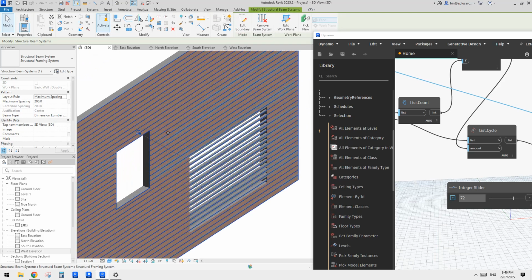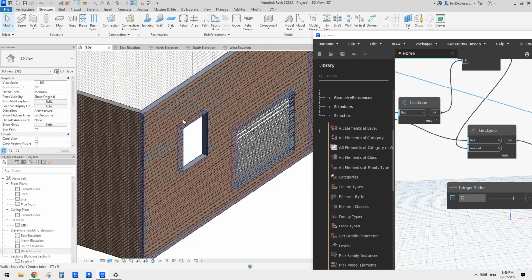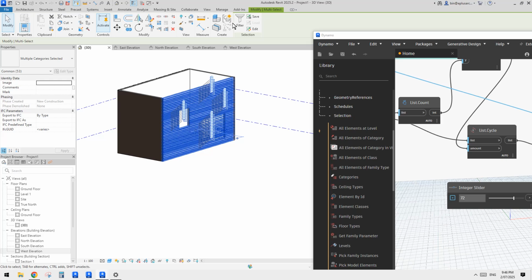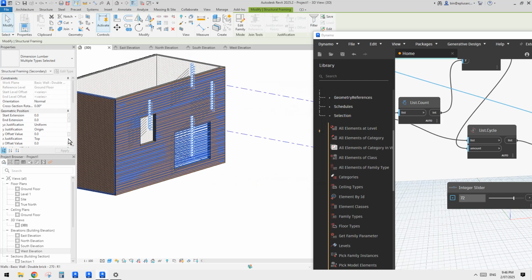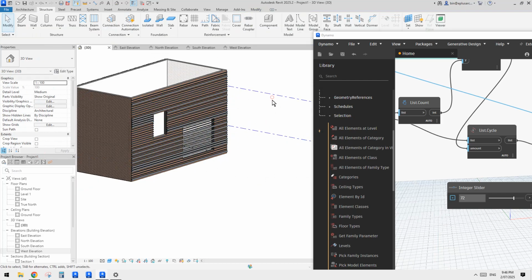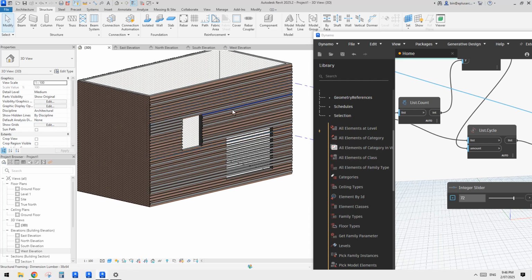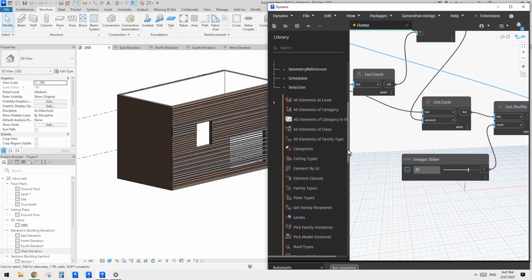Yeah, good. So again, you can see that inside of the wall, but this time maybe I'll just select them and filter. I'll just unselect wall, beam system. Yeah, select all the structure framing. I'll change this one to bottom. So that's it. Okay, and then we can just do the same thing, or actually you can see it automatically changes because I have this Dynamo on automatic.